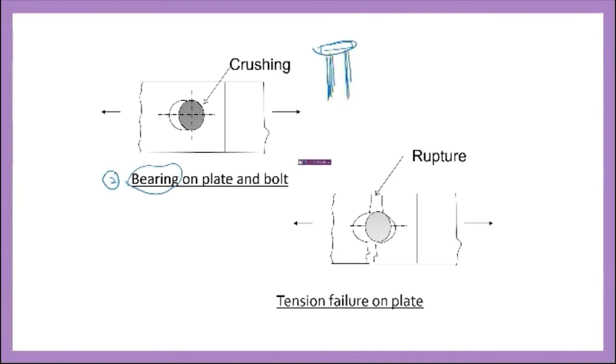Maybe the bolt size is bigger and you don't provide a suitable hole diameter for the plate. When a force acts on it, because it is too big and not suitable for the hole, it will pull. Or perhaps when the hole is too small, the bolt is free to go left and right and up and down, because there is a space that doesn't fit the hole, so it moves more easily. When a force pulls it out, the bolt will pull the plate along. The bolt will crush and break.